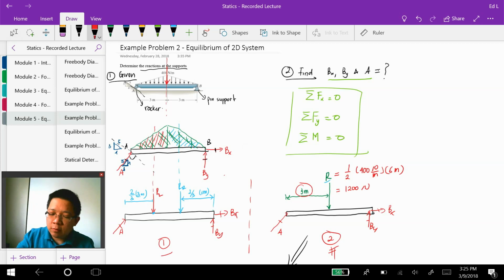Option 1: two resultant forces, RL and RR, based on the left side triangle and the right side triangle. The second option is to calculate the resultant force based on the entire triangle, which is symmetric at the midspan of the beam. So we can calculate the resultant as the area of the triangle, and it's located at the midspan because that triangle is symmetric about the midspan.